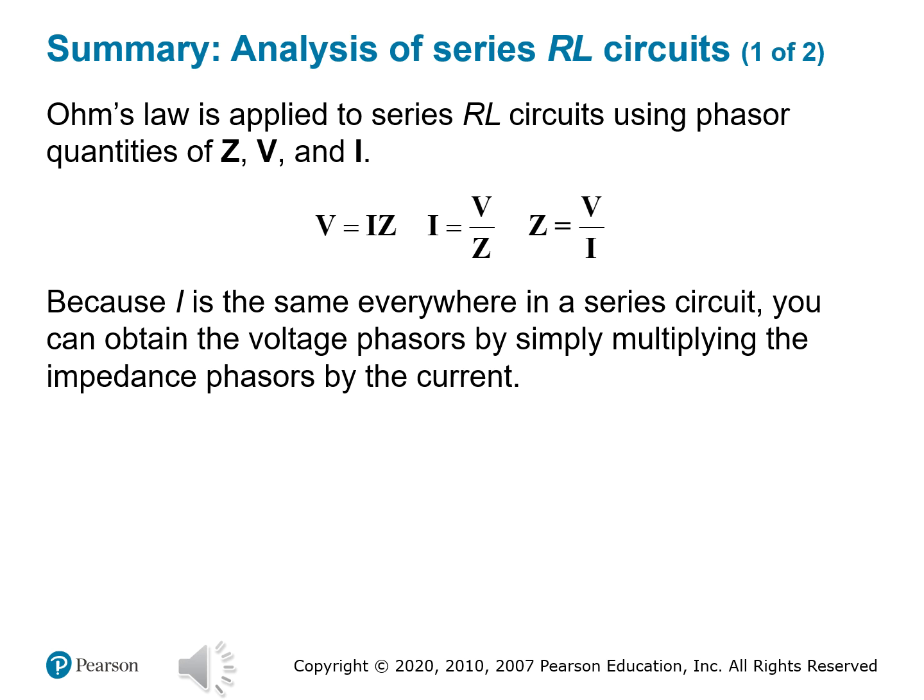In a series RL circuit, Ohm's law takes the phasor form: V is equal to I times Z. Again, remember Z is now being used as impedance in place of resistance. V is the total voltage phasor, I is the current phasor, and Z is the total impedance. It includes both R, resistance, and inductive reactance, which we denote by X sub L. You can also rearrange this equation just like you did in DC circuits: I is equal to V divided by Z, or Z is equal to V divided by I. The math may look familiar, but now the quantities carry magnitude and phase.